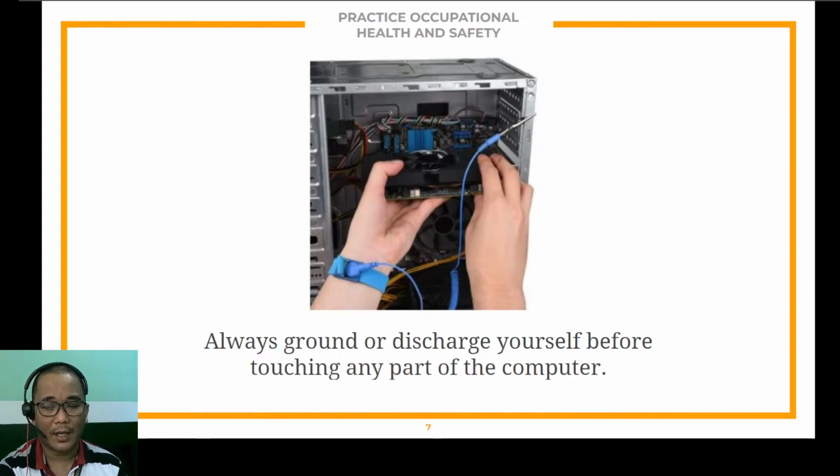Or in other ways, before touching any components of the computer, you can discharge yourself by touching any metal aside from the computer, so that whatever electricity within yourself will be discharged. So better to be safe, for you to avoid damage on the computer parts.